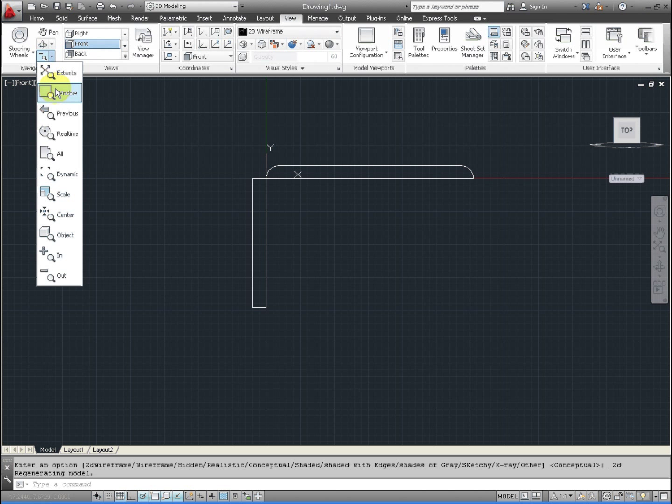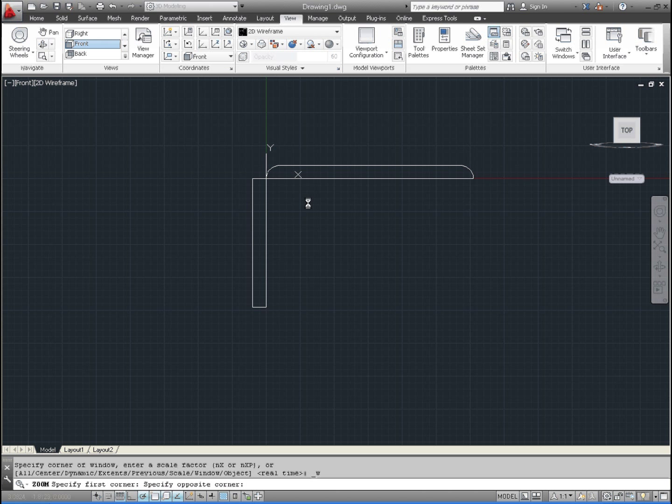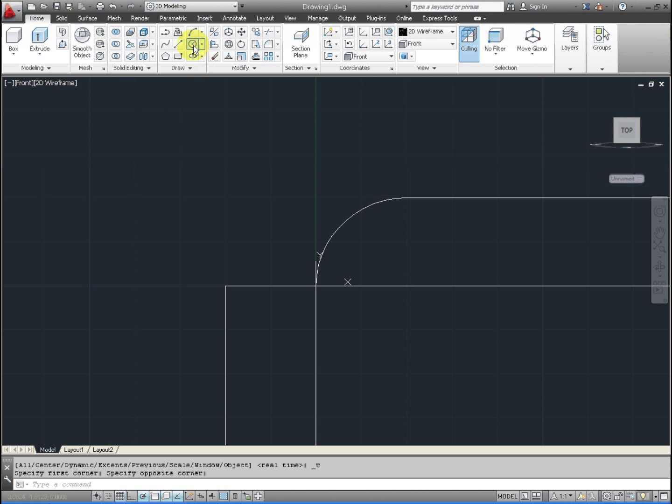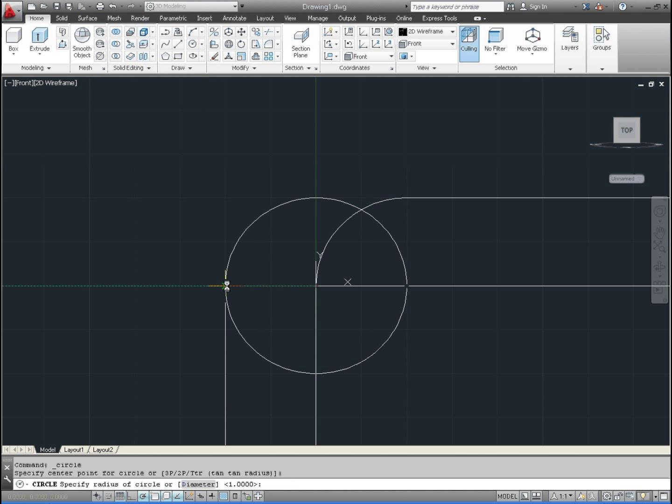And so we're going to do a similar thing. Let's go ahead and zoom in on this so we can really see the detail here. So we have the one bullnose edge, but we actually need to make a cavity with this rectangle we just made. So we're going to do the same procedure as we did on the top to make the bullnose. Take the circle and put it on the rectangle so it's 1 inch in radius.